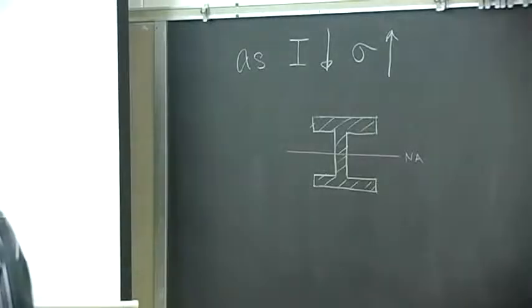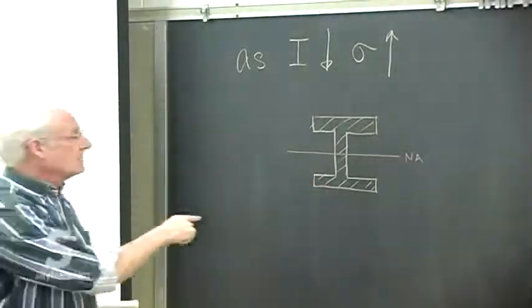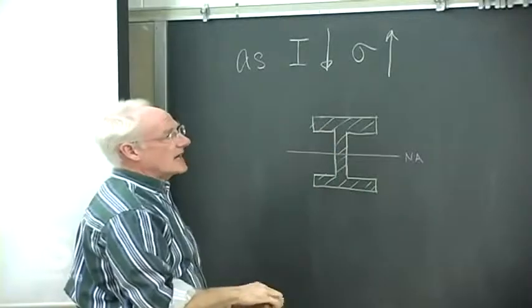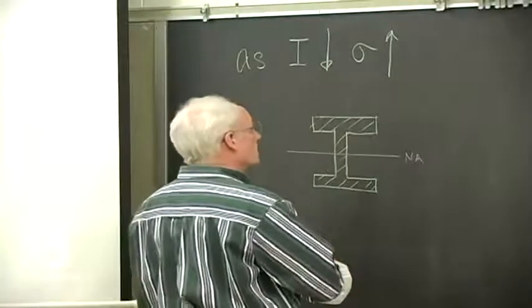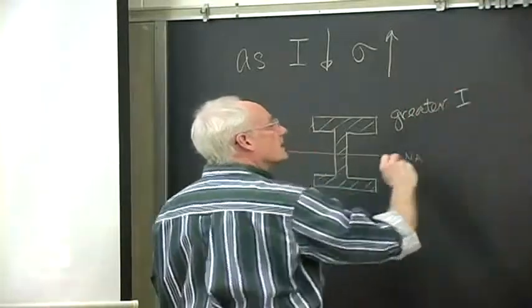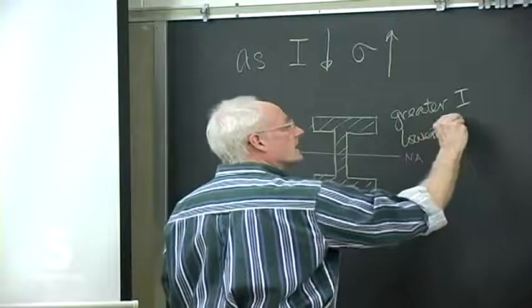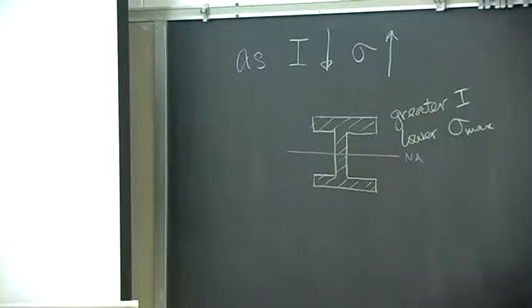which we need to resist shear, we have the same area, but we have a much greater moment of inertia with an I-beam because of this additional area away from the neutral axis, as we'll remind ourselves here shortly, doing another calculation of finding this. This greatly increases the moment of inertia. Gives a greater I and a lower normal stress. So that's why we use I-beams in construction.